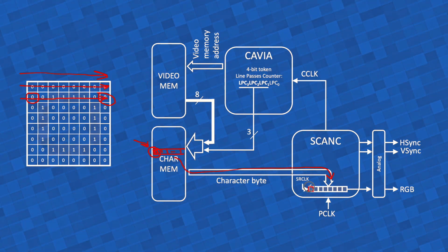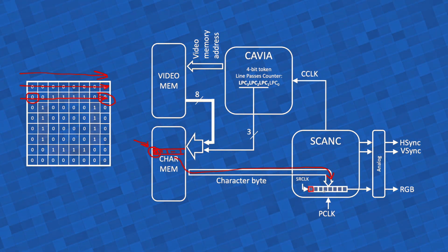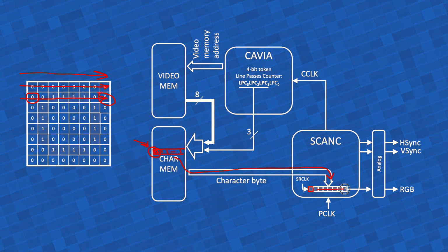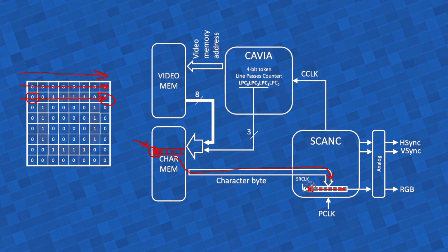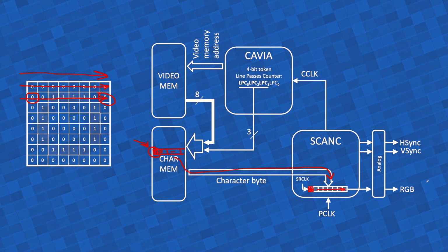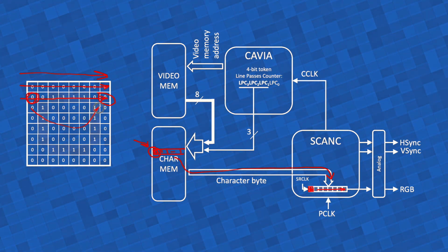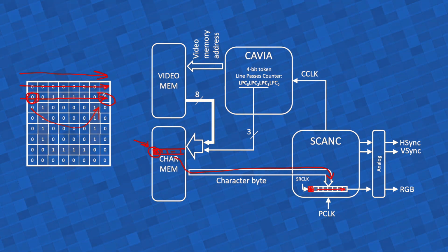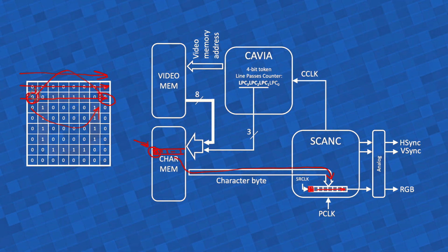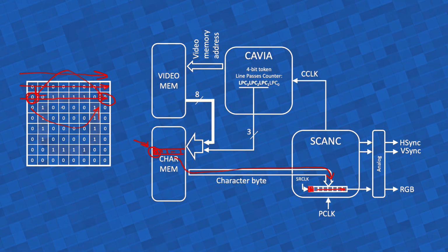If I don't flip it around, it will end up here. And since the shift register is shifting to the right, the most significant bit will be the last one to be printed. So this guy will actually be printed in that position. And this guy, since it will be the first, will be printed in the first position, and the characters will be mirrored.